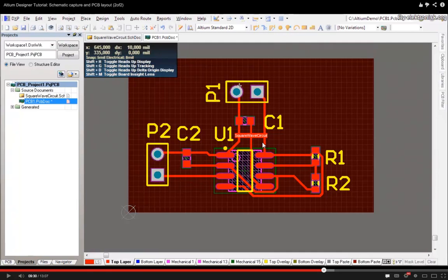Everyone will have, I assume, their own thoughts and their own restrictions. And then you would want to wire them up with route or wire or lines. It doesn't really matter. You click them, and you can just drag them along the red part. These are all the pins. So these are the holes that will be created for your component. And you just wire them up according to your schematic files. And once that's done, then it's done.